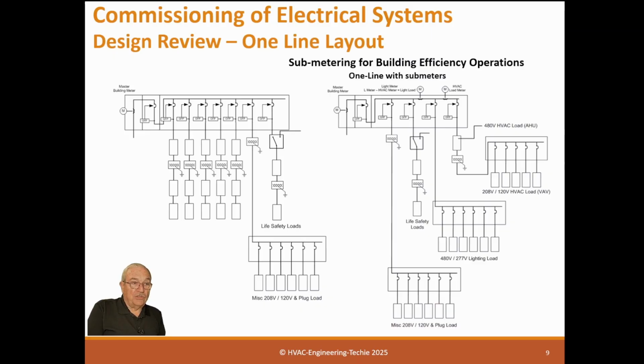So you can't actually do much with plug load. I mean, people won't let you unplug stuff, so you're pretty well done. And lighting, the only thing that happens with lighting is schedule. So once you get the schedule set, lighting isn't going to change, but HVAC does. So this metering is really important.